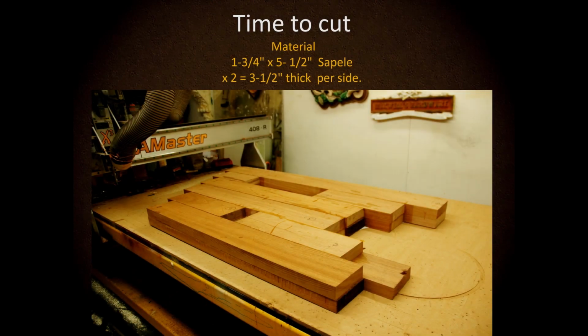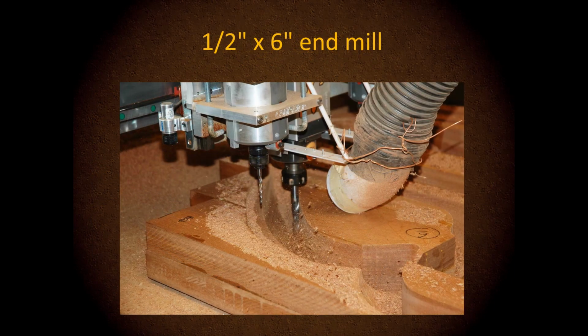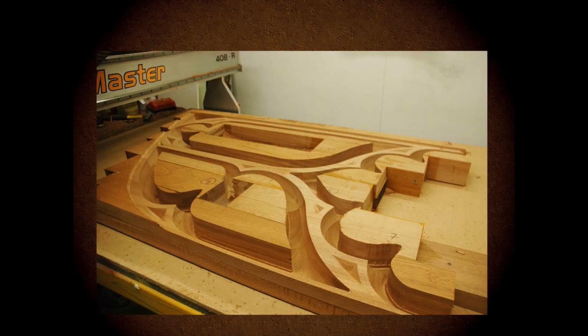So here's the real world situation outside of the software. Here's my lumber, sapele, glued up. This is the roughing cut. I used a 1/2-inch end mill, 6 inches long. This is what it looks like after the finished cutting is done.